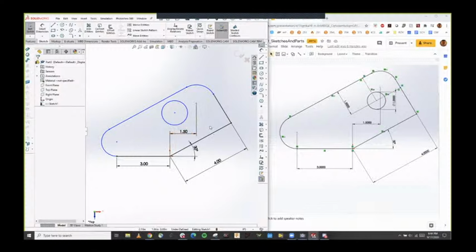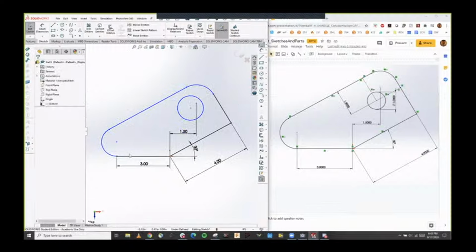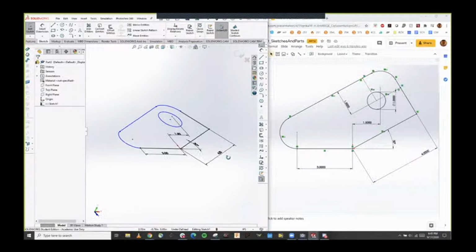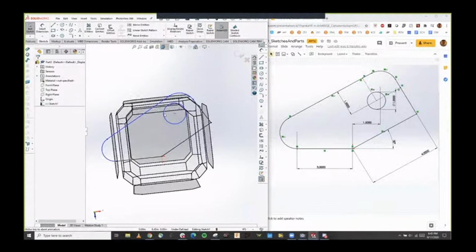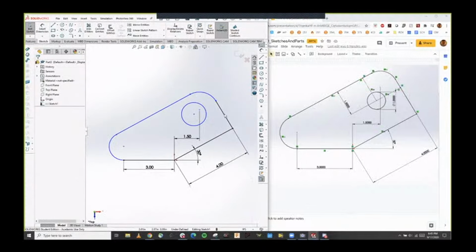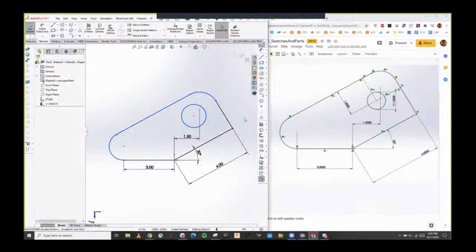A lot of the stuff that is left for us to do, however, you can see are these dotted lines and these dimensions, this dimension on this dotted line. So what are those dotted lines? This is a construction line. Every solid line that you see right here is an actual defined line, and these lines define the outlines and features of parts. A construction line, however, is a reference line that we use to place these features in their specific locations.